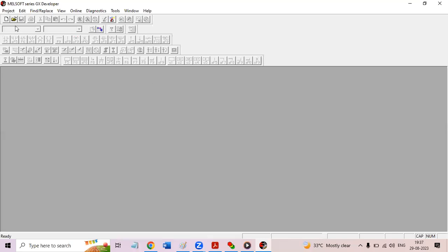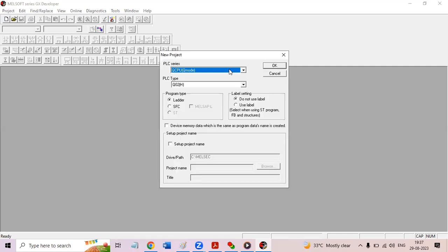Very first we take a new file. In the new file you see in Mitsubishi, these are the CPUs. This is the series. So you have Q CPU, in Q CPU, Q mode, A mode. I had told QNA CPU, A CPU, right? Motion CPU is for motion control, that is for robotics, for axis control. Motion CPU is used for axis control basically. FX CPU, just now I have shown you the Mitsubishi FX2N PLC. So it is of the FX series.